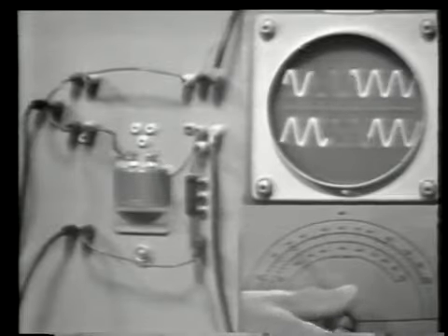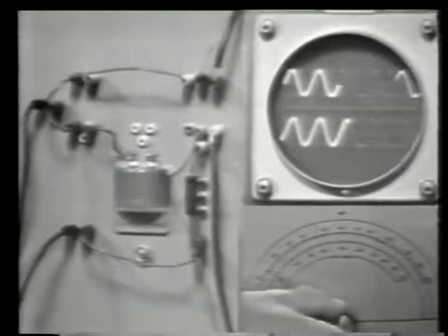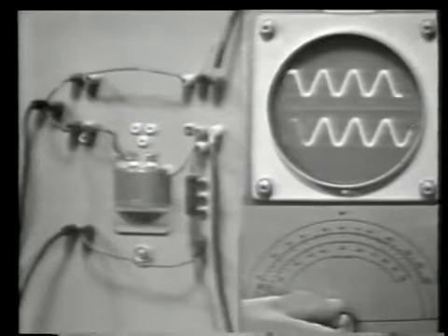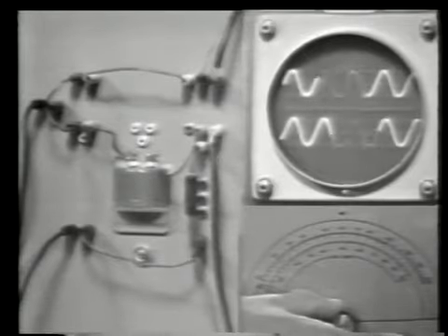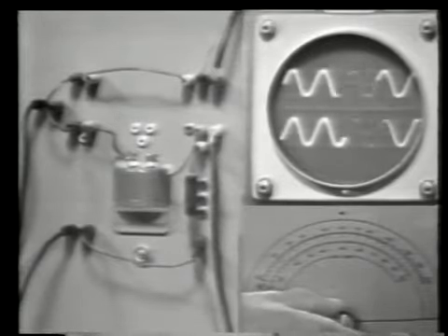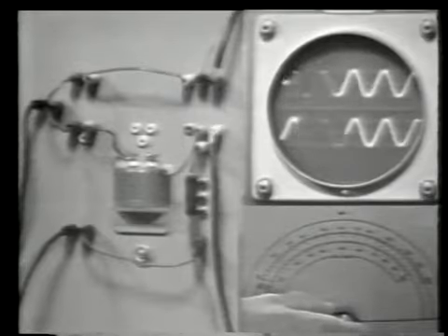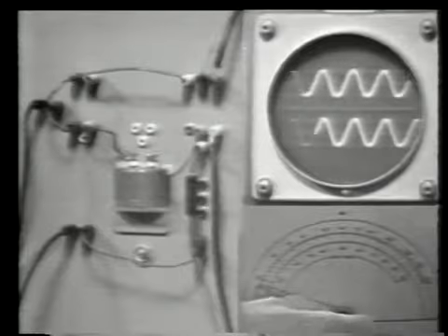Now you'll notice down at the low frequencies, I'm down around 200 hertz now, that I do have an output. I have 10 volts on the input directly from the signal generator, and on the B trace, the lower trace, I show 10 volts of output from my filter circuit. So we're passing the low frequencies because this is a low-pass filter.